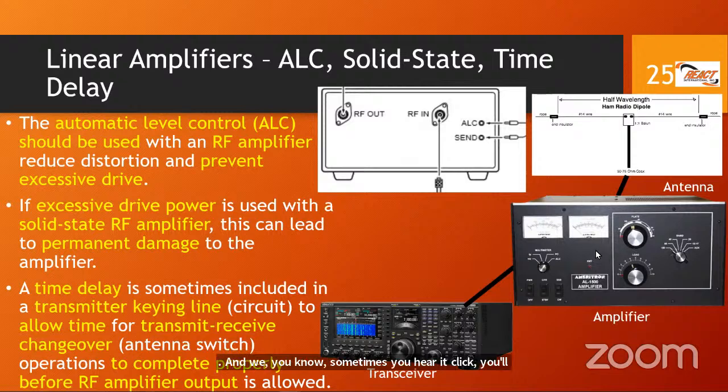That's the little delay. You need to be aware there's a little delay, not a very long delay, but that's why also when we're operating radios, we don't start to speak as soon as we key the microphone. We need to be aware of those little delays inherent in signaling and take that into account. So we take a little breath before we actually start to speak, or we use a little precursor. That way the first syllables of our message will not be truncated.